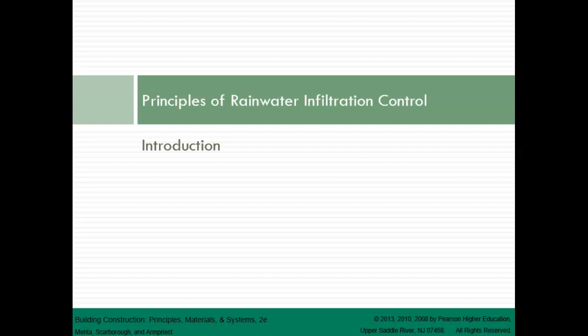They must control heat loss and heat gain. They must control air leakage and water vapor transmission. They must resist fire. They must control sound transmission. And they must accommodate movement due to thermal, moisture, and other causes.